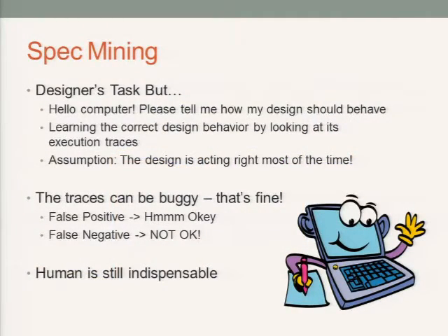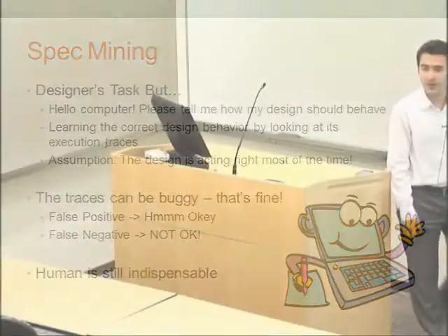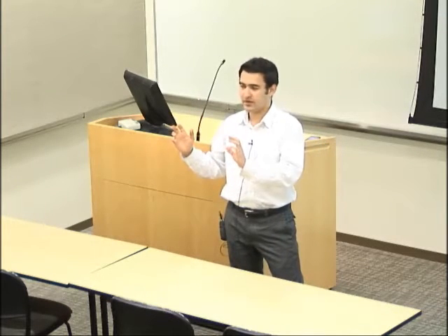When you get an assertion, what do you do? We check for its correctness. Okay. Check for the correctness of the assertion. So the assertions can come in any kind of logic statement, but the kind of statements that are common now are linear time logic. An example would be: if this event happens, it has to stay valid until the other event happens.